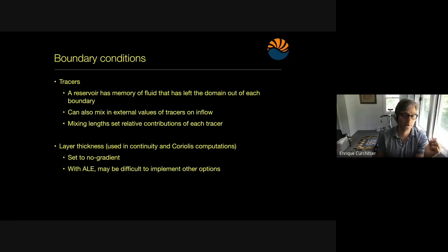Tracers, this is still an emerging development. There are prototypes for this now. There's been a lot of work done in the last few weeks, and this is coming online hopefully in short order. The way they've been designed is to have a reservoir that has memory of the fluid that left the domain, and then as information comes in, you can then mix it, and you can set up mixing lengths relative to the contribution of each tracer on the inflow.